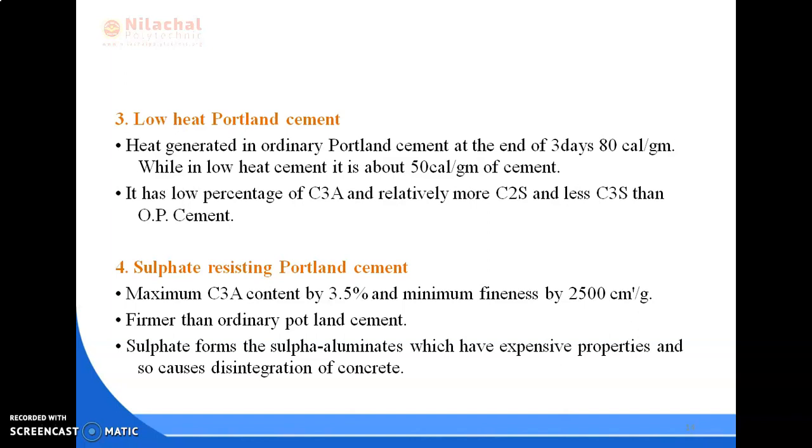The clinker of cement is ground with about 60 to 65% of slag to form this type of cement. Its strength in early days is less and hence it requires a longer curing period. This type of cement proves to be economical as slag, which is a waste product, is used in its manufacture.